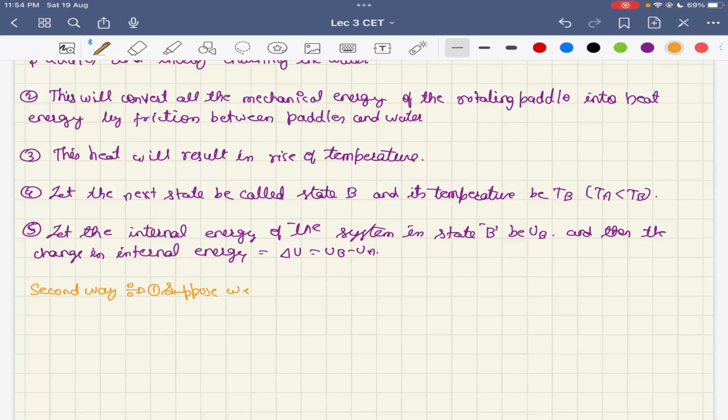In fact, Joule performed a series of experiments during the years 1840 to 1850 to find the relationship between mechanical work and heat produced. By performing careful experiments, Joule found that a given amount of work done on the system, no matter how it has been done, irrespective of the path, always produced the same change in state as measured by change in the temperature of the system.